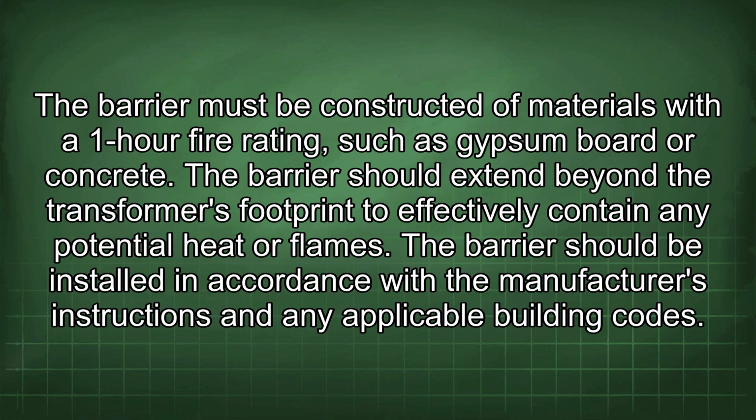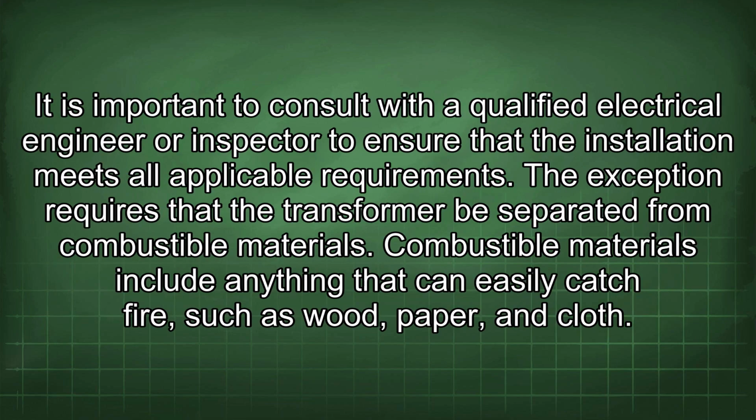The barrier must be constructed of materials with a 1 hour fire rating, such as gypsum board or concrete. The barrier should extend beyond the transformer's footprint to effectively contain any potential heat or flame. The barrier should be installed in accordance with the manufacturer's instructions and any applicable building codes. It is important to consult with a qualified electrical engineer or inspector to ensure that the installation meets all applicable